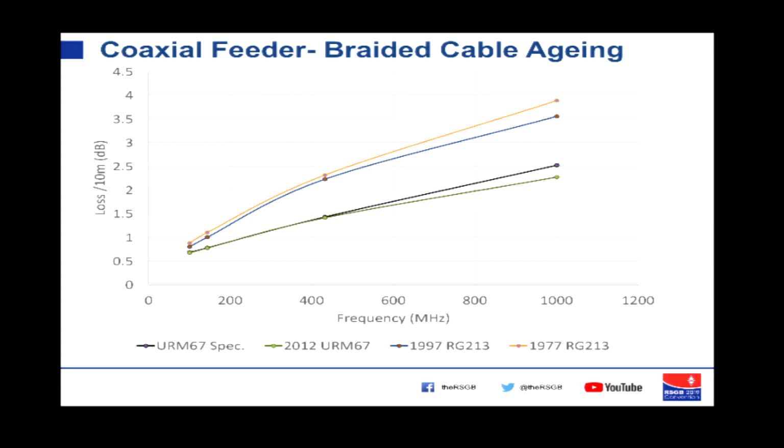And here's a bit of it. I'll hand it over and hand it round, everybody inspect it. Gradually, water gets through the braid. Gradually, the PVC, under the influence of sunlight, starts to, what should I say, emit plastic things that make the braid more resistive than it should be, and the loss goes up. So the message is a simple one.